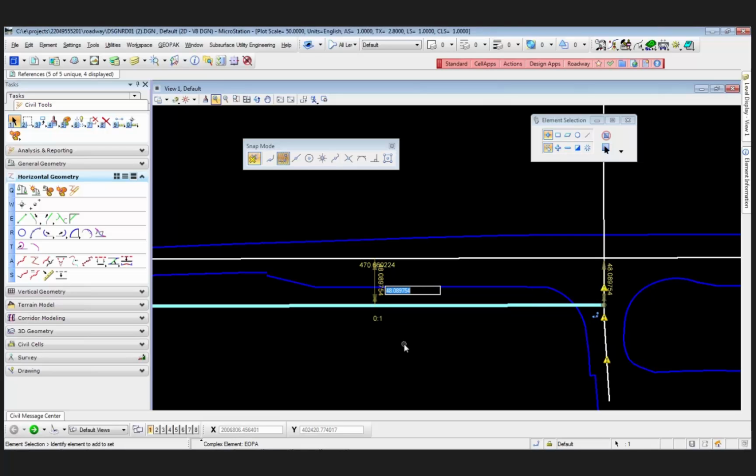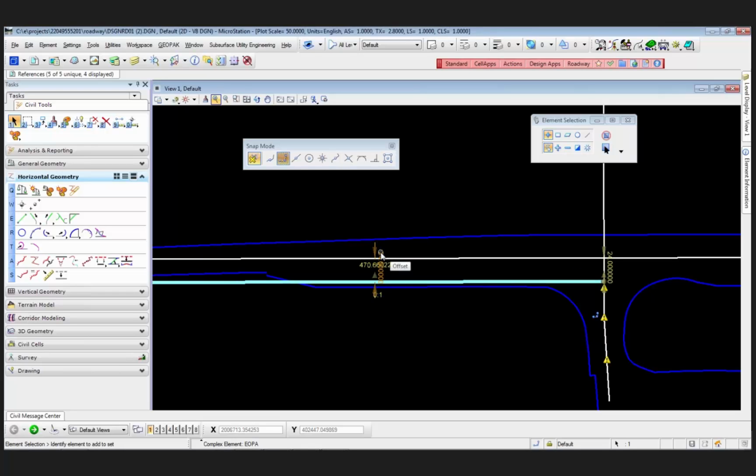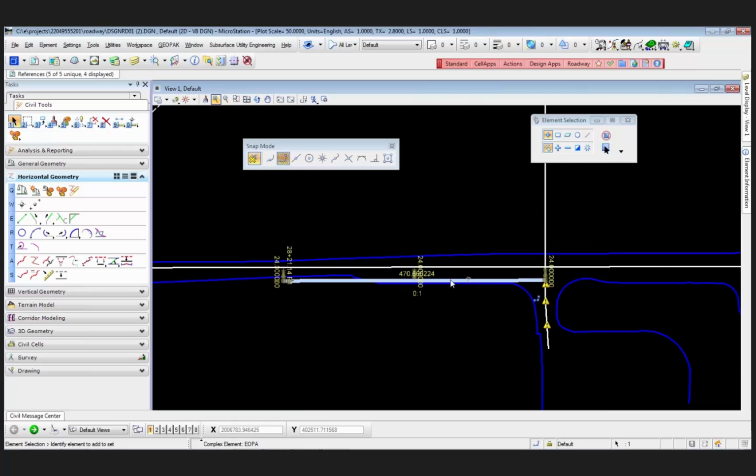And in this case, I can change it from a 48 foot offset to just say 16 feet or 24 feet, however. And then I can also change the begin station to a specific number, 2800, and it moves the line back. If I want to change this length, I could change the length to 500 feet, so it's an even length. Or I could go in and change the end station. The point being is it's more than just copy parallel, because it has intelligence to it as a civil element.